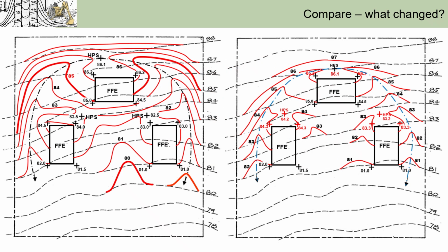Lastly, let's put these two drafts side by side, and you can see that the second draft is not that red anymore. There is much less contour movement here. So iteration is really key to any grading project. It can lead to a major improvement of the quality of the space and significantly reduce construction cost. Okay?